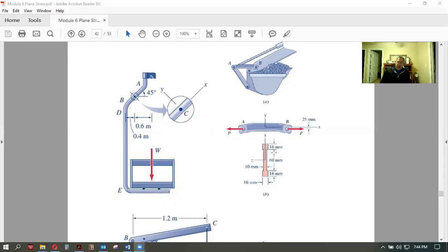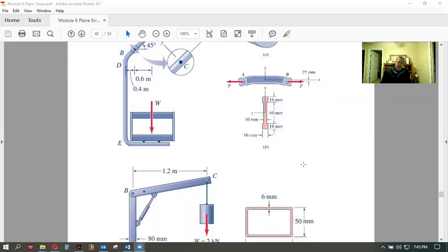So if you've got these 2 sets of forces that are pulling and they're opposed, right, it's a 2-force member. Well, that 2-force member is going to try to elongate, but its whole orientation is not in that straight line from A to B. So it's going to try to straighten out. It's going to try to bend as well as elongate. So there'll be a combined state of stress in that linkage piece.